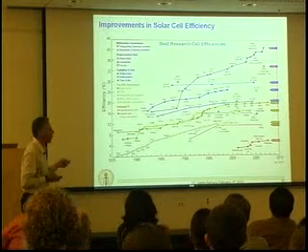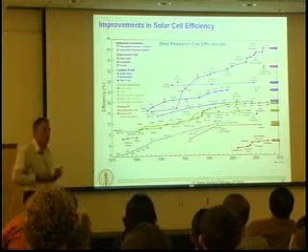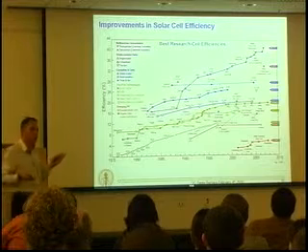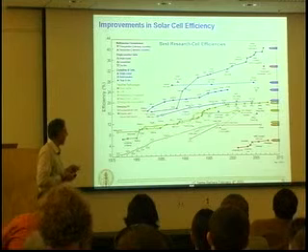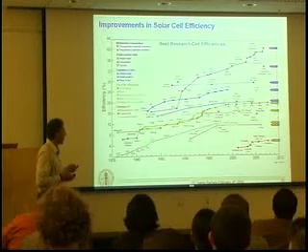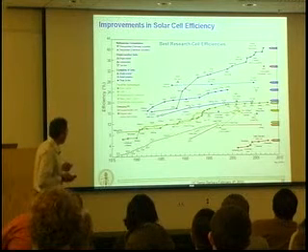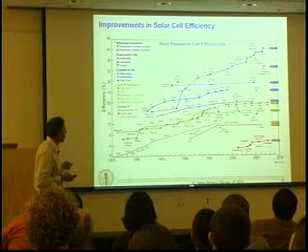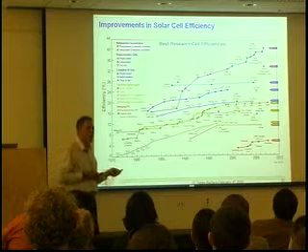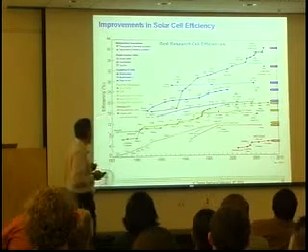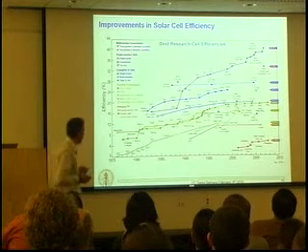The last record efficiency was set in 1998. And that tells you that basically we've harvested what device physics and solid-state physics have given us from homogeneous single-junction silicon cells in terms of efficiency. And commercially, we're approaching this efficiency of just under 25%. What's quite exciting here is to see that the multi-junction solar cells have been increasing their efficiency, and now record efficiencies are over 40%. In fact, the most recent record from the Fraunhofer Institute is 41.1% for heterostructure solar cells, multi-junction solar cells.